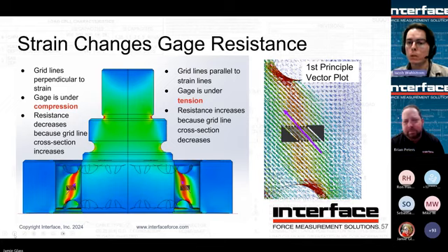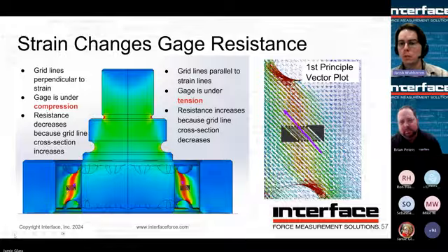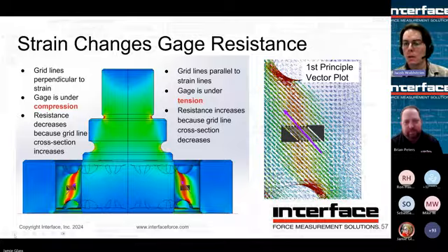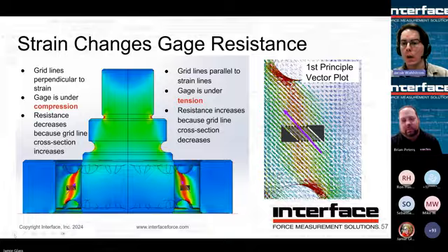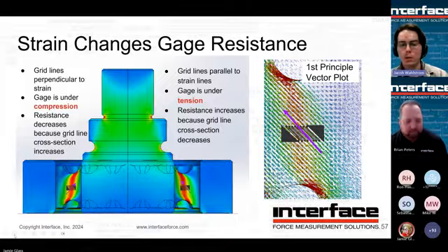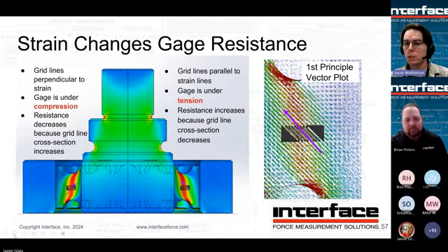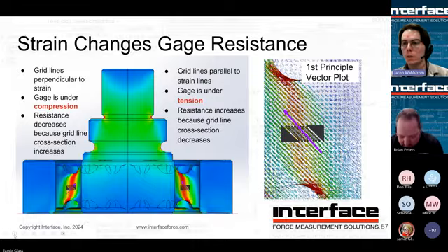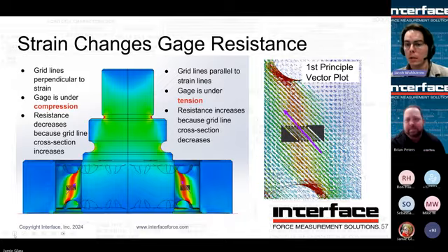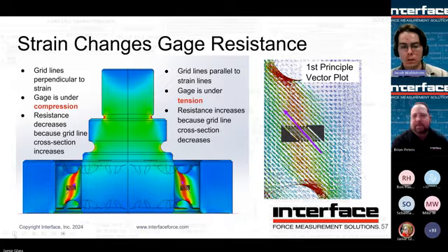So that's a good point too to bring up the 1800 series, because not only do they get the integral stud, they also get double gauges, and you can see that the nonlinearity of one gauge being misaligned one way or the other is somewhat random, right? So by doubling the amount of gauges, it can help cancel out any nonlinearity issues. That's 16 gauges, right, per bridge? Yeah, so 16, quite a bit, per bridge on 1800s. Alrighty, thank you, Brian.